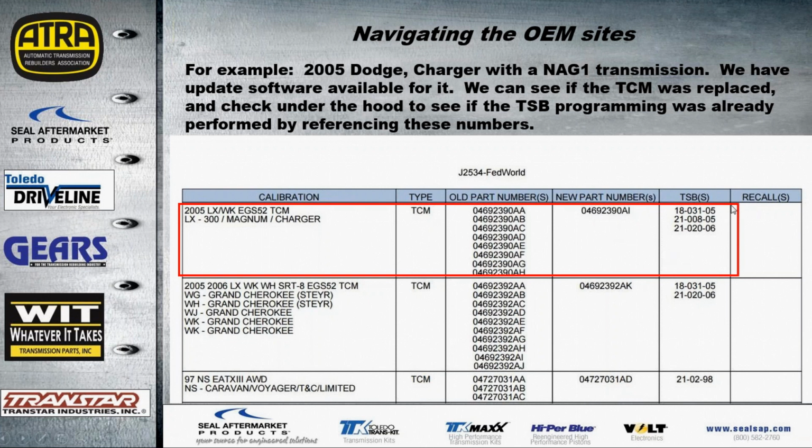And the technical service bulletin searches can be done just by entering these numbers in. You can even enter these in on Google, and a lot of these TSBs will come up directly on Google. So that's a wonderful tool to invoke because some of these you have to go into the website and purchase a subscription to actually obtain some of these technical service bulletins, and that's mostly the very latest ones.